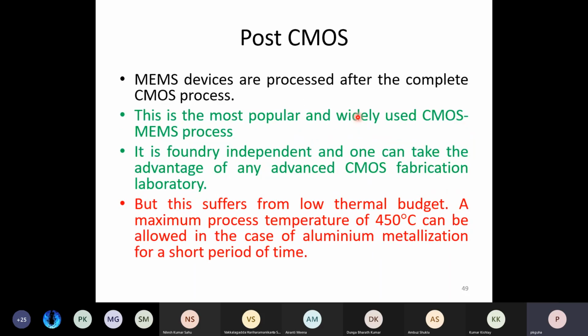So what you can end up with, most of the labs use post-CMOS integration, where this carbon nanotube fabrication was a post-CMOS integration, as I showed you. So we already have your IC, your fabricated circuits, then you develop your sensor and other devices in a specific place. Okay, but if you do that, you have to make sure there is a thermal budget. You can't use any temperature you want, you can't use very harsh chemicals, because that can be detrimental for your circuit.